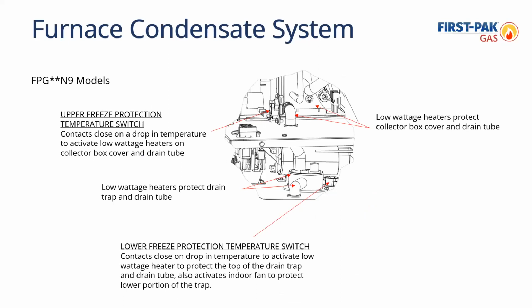This just goes a little bit into, there's also a blower function that it will turn on the blower if it senses, in addition to the heaters coming on. It will turn it on to circulate the air to try to warm up the temperature within the furnace section of the unit. So that's another nice feature, again, to help keep that condensate from freezing up in the colder temperatures. And Zach, I don't know if there's any questions or if you want me to, I'm going a little fast here. No, you're great.